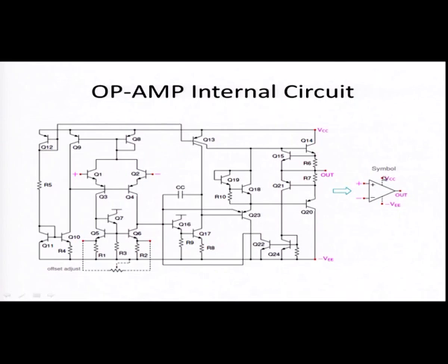And here you can notice the positive supply and the negative supply. This VCC is the positive supply, and this minus VEE is given for the negative supply, and the output you can take in between the resistors R6 and R7. So, this operational amplifier IC741 is made up of n number of BJTs, or this IC741 can also be made using field effect transistors.